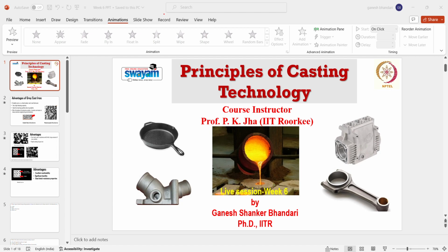If you want martensite in your system, then you have to rapidly cool down that steel after heat treatment to form the martensite. So we talk about eutectoid steels and we talk about eutectic steels in the systems. The point with 0.8% carbon is known as eutectoid steel.